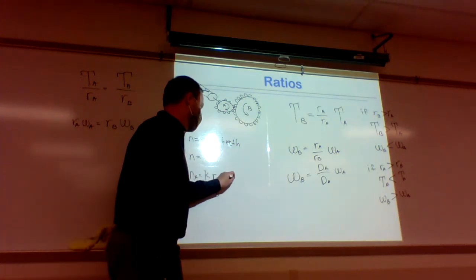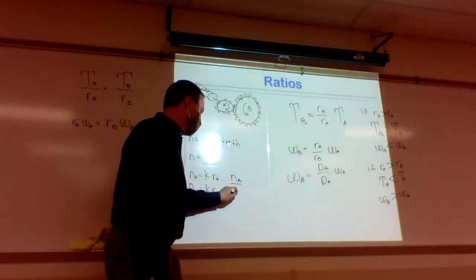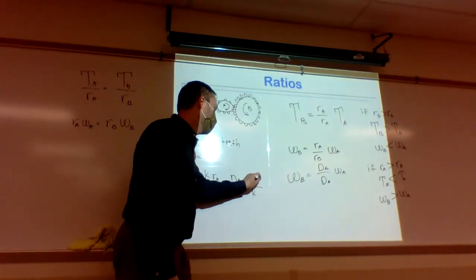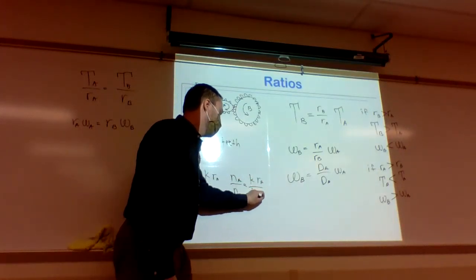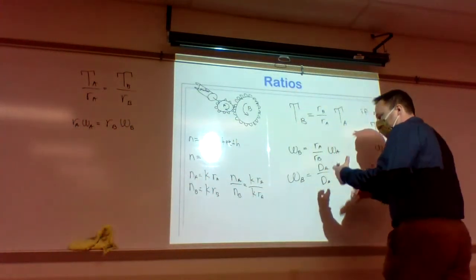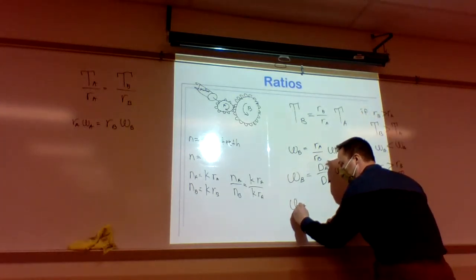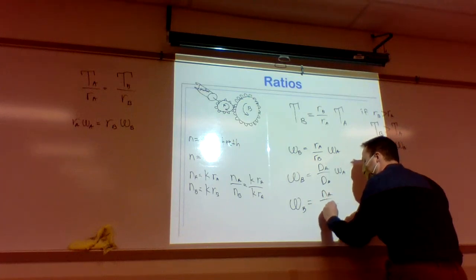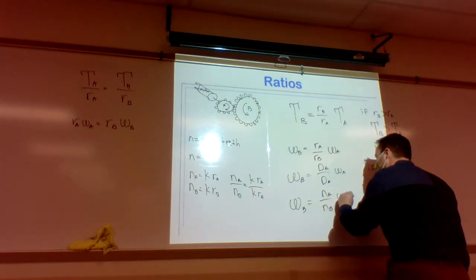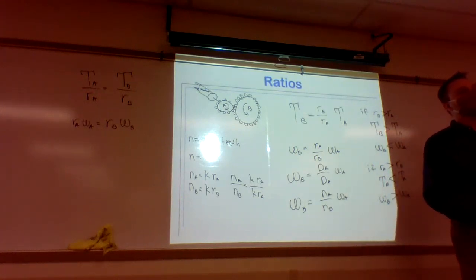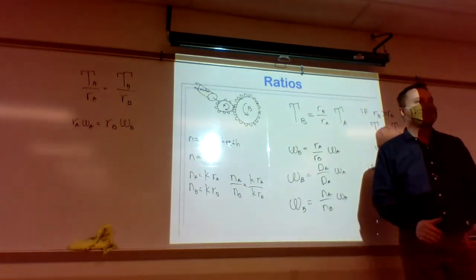And so notice what happens when I put a ratio here. The number of teeth on A divided by the number of teeth on B is going to be the same constant, top and bottom, divided by the radii. So if the gears are actually designed to mesh together and they mesh together well, then you could actually just count the number of teeth and the ratio holds, assuming they're designed to mesh together, assuming this constant's the same.